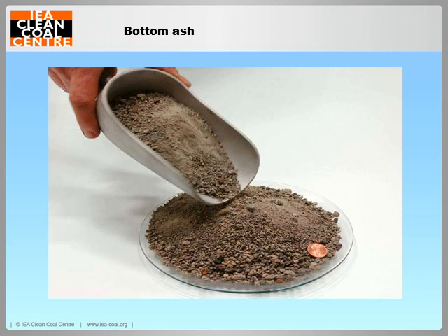One of the most common uses for bottom ash is as a structural fill material. At many construction sites, large quantities of fill are frequently required to level low places for construction and drainage purposes, build embankments, fill trenches, backfill foundations, etc. The fill is typically local aggregate or crushed stone. Bottom ash is commonly used in these applications if it is available and close enough to be transported economically.